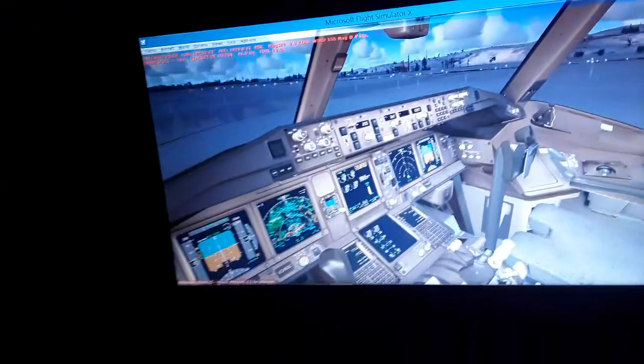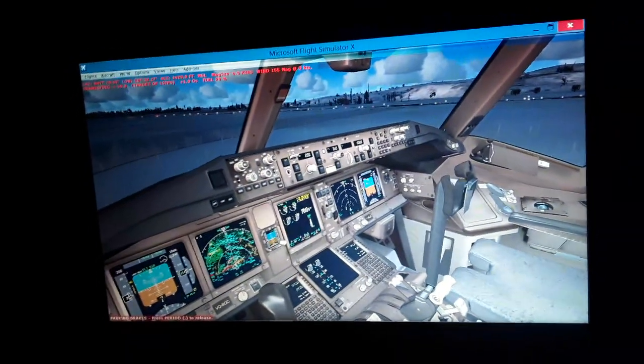We're going to have the ILS localizer, the horizontal localizer, and the vertical glide slope, the instrument landing system, its frequency. So the aircraft is going to be guided with that for landing, either manually or automatically using the autoland. So I'm going to show you this manually. Then I'm going to show you the autopilot and flight director system panel.